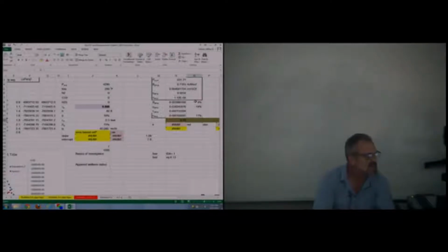So basically, from a volumetric standpoint, 4% error. I know this textbook uses a different gas viscosity than I do, so I'm always going to get a pretty good size error with viscosity and my CT. So when I don't get exactly the same numbers as a result, I know a little bit why. But I want you to get used to something that you can always pull up. You're never going to be given a real world problem where someone's going to tell you what the apparent pressure at 1 hour is and go with that. You're going to have to calculate all these things.